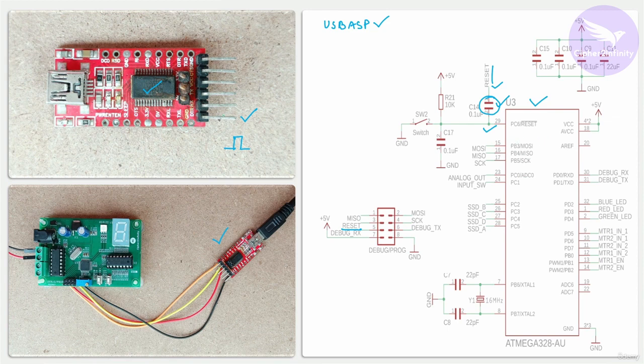So this is basically the second method to program the microcontroller using this USB to UART converter. And remember, this capacitor is very important, and if you don't connect this particular capacitor here between the DTR pin and the reset pin, then you won't be able to program this controller. Okay, so this capacitor is actually a very important element.